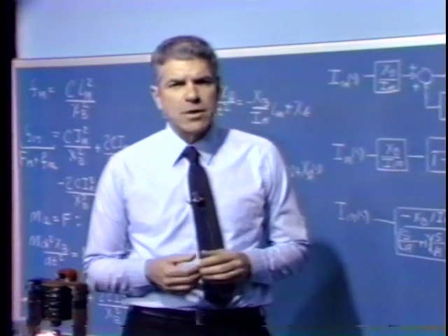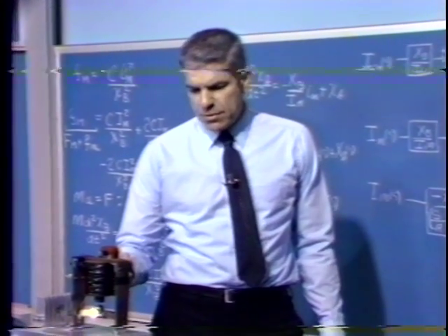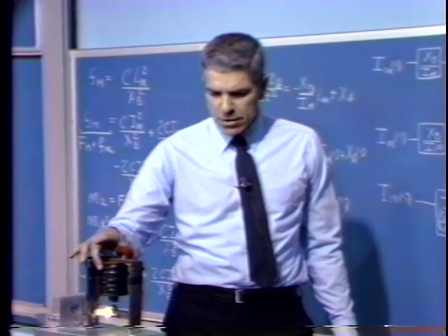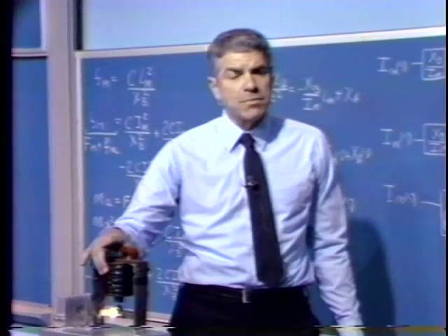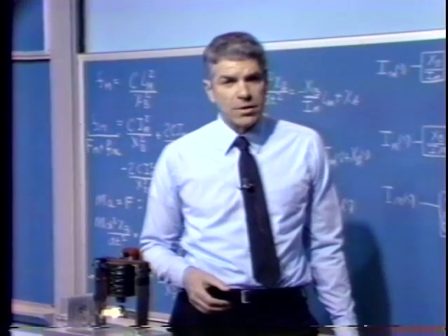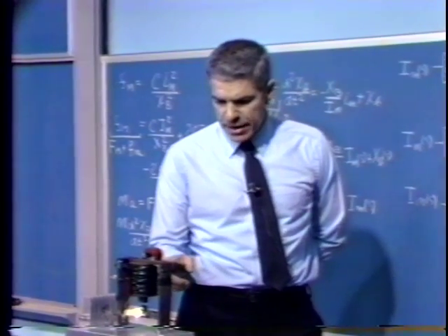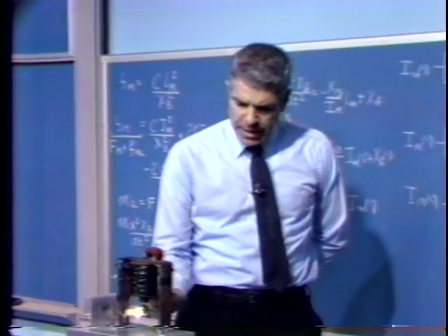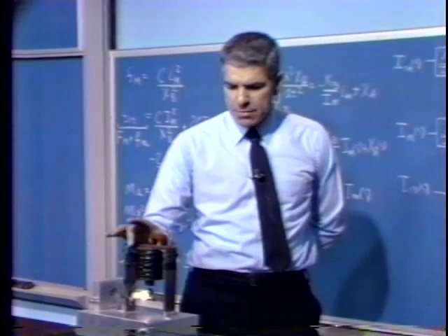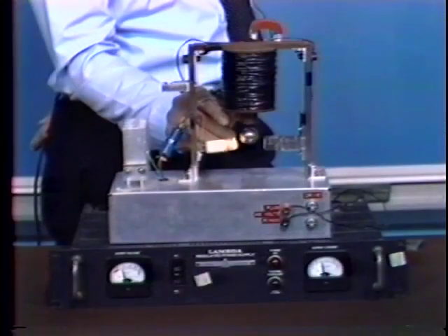There was a group at Lincoln Laboratory that was worrying about this. And they used a magnetic suspension system, but again, you'd prefer not to have to spend a great deal of power in the magnet. You'd prefer not to have to use a large electromagnet as I have, because the power to drive that electromagnet would have to come from somewhere, and you're trying to improve the overall efficiency of the system. So what the people at Lincoln did was use a permanent magnet and put a winding on it, but now there's a null position. You can select your operating point to be that where the force associated with the permanent magnet just balances the force of gravity.